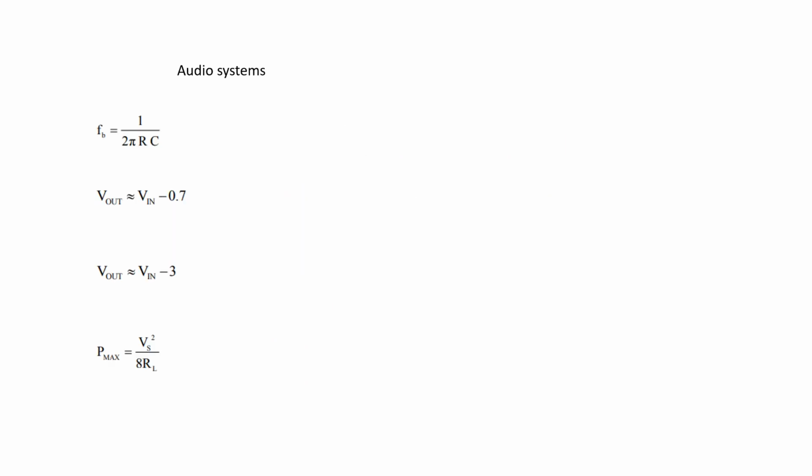Okay, just to finish then, audio. You've got your 4 filters, and you're going to be using that to find your break point. Remember what they look like. The capacitor could be in 4 different places. Try and remember what happens with the capacitor. Try and think about what it does. Capacitor: low frequencies can't get through, high frequencies can get through.